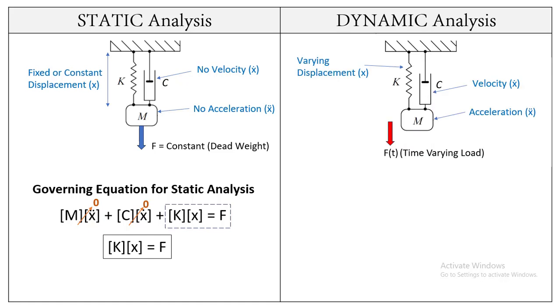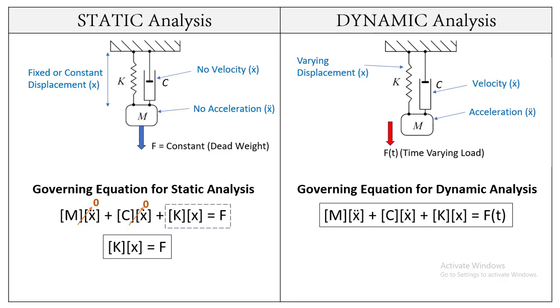When we talk about the dynamic analysis, you can see in the animations, since the displacement is changing with time because of the time varying load, there will be some velocity and acceleration in the overall system. So we will get the governing equation for the dynamic analysis: the sum of the inertial, damping and stiffness force is equal to the time varying load.